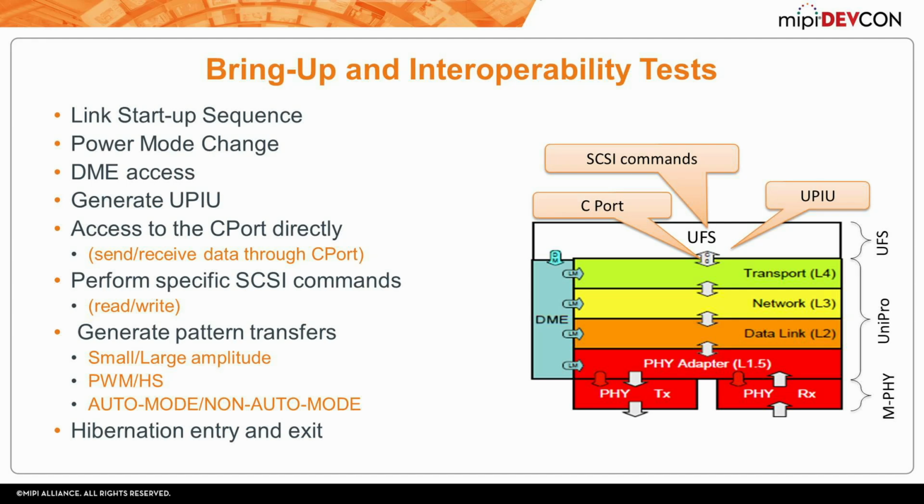Here are some of the bring up and interoperability tasks that you can do between your host and your device solution. I chose these because of their importance, but it's just a summary. There are more, of course. When you have these tasks working, you have some confidence in your solution. It's important to notice that these tasks are not easy and fast to perform, like the link startup sequence, power mode change, DMA access, or hibernation entry and exit.